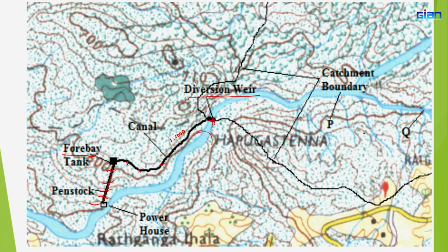Identify a contour location, basically how to develop a hydropower plant. Then there is a concept of how much water can come into this diversion point. That is a good question. That depends upon the rain upstream. Not all the rain will come to it, only certain lands above this point which slope into the river can collect water into this. So, this gives the idea of catchment area. This is called the catchment area.